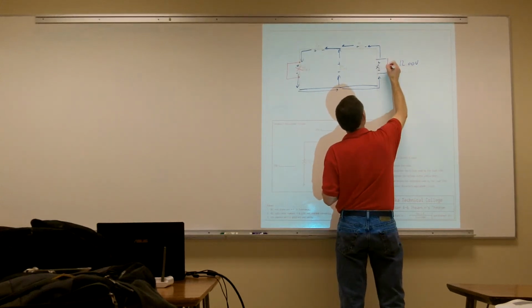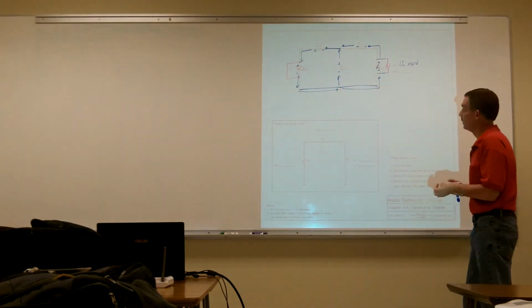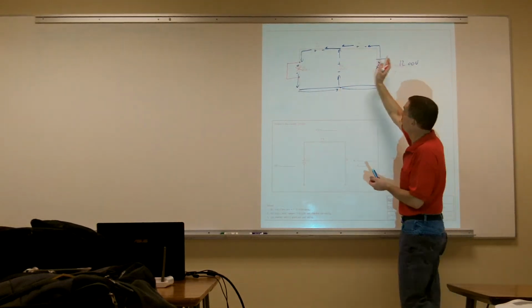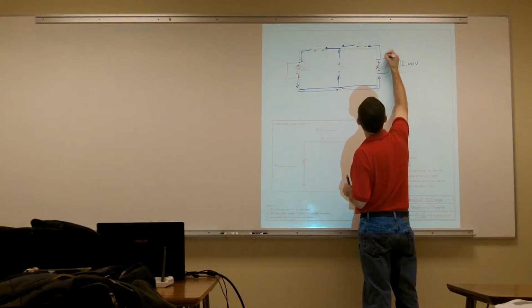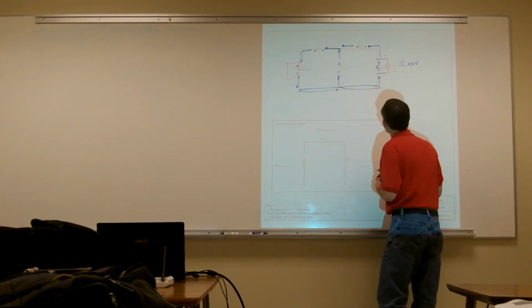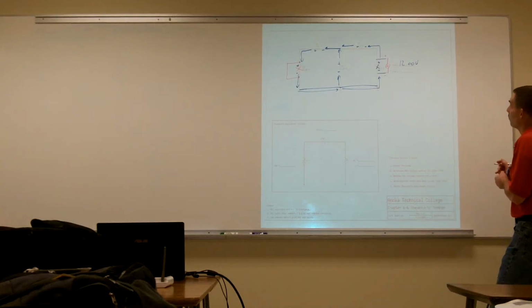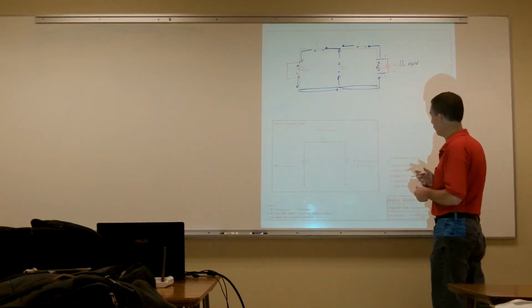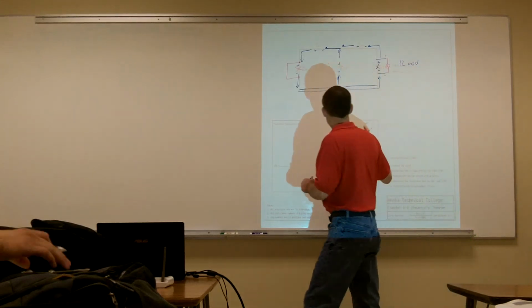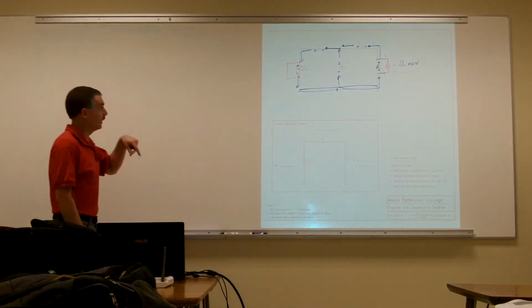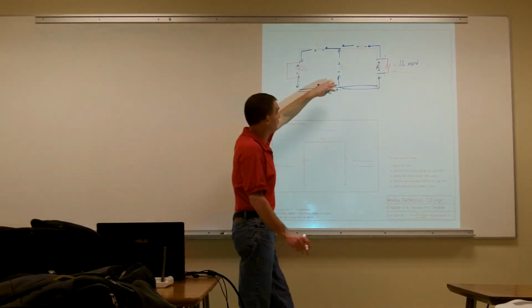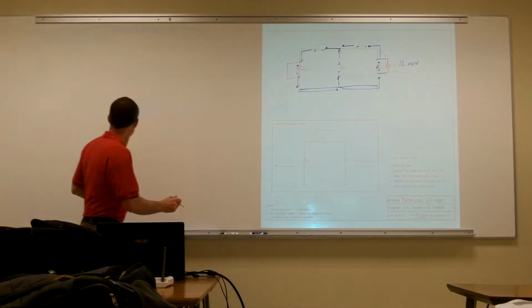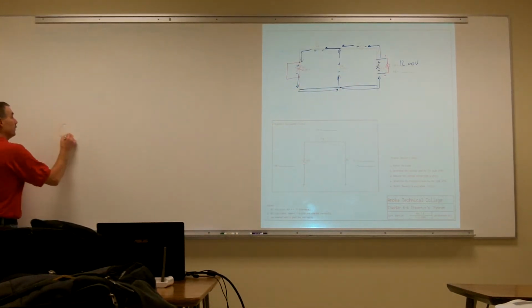with an ohm meter. Now remember, these ohm meters have their own internal power supplies, and they're going to be setting a current going through here. So for example, we can put the positive and negative of our ohm meter. It really doesn't matter when we're measuring resistance since there's no polarity, but to give ourselves some kind of direction to find out how to reconfigure the circuit. So our ohm meter now becomes actually our voltage source for this particular circuit. So I'm going to draw in our ohm meter here. That's going to be our voltage source.